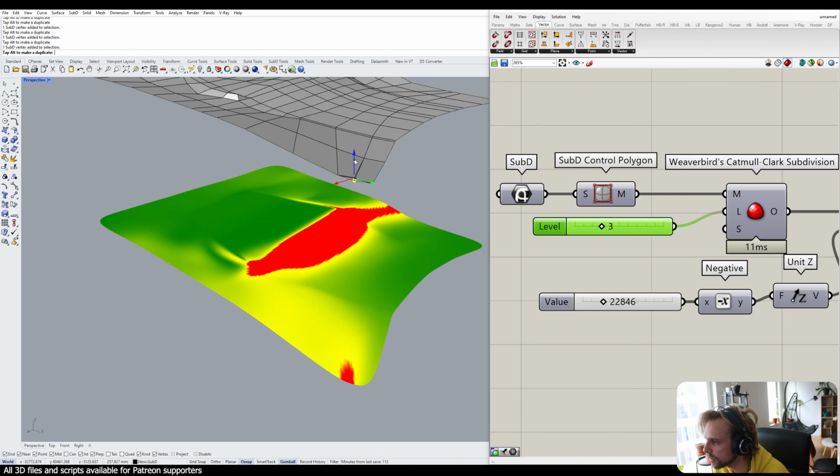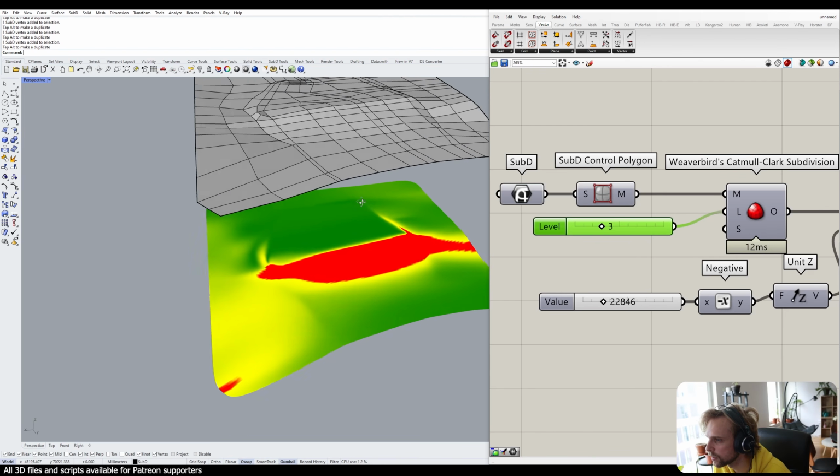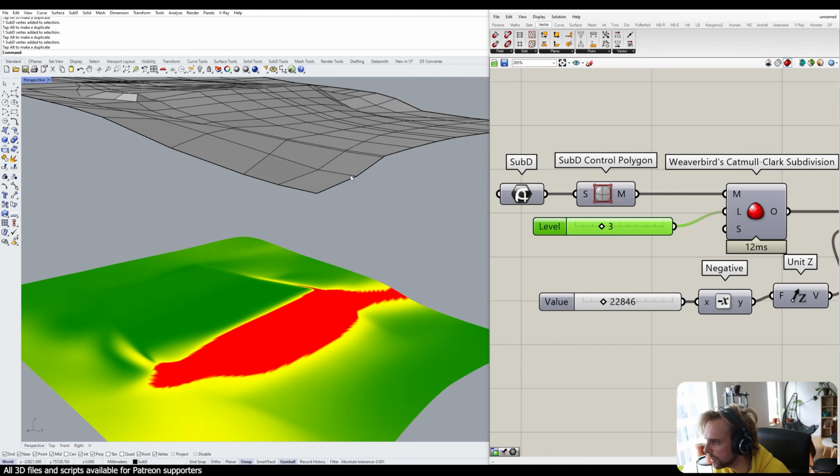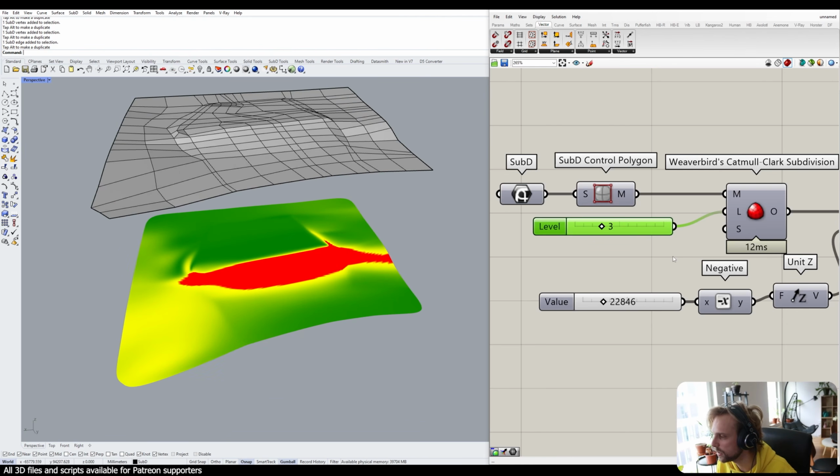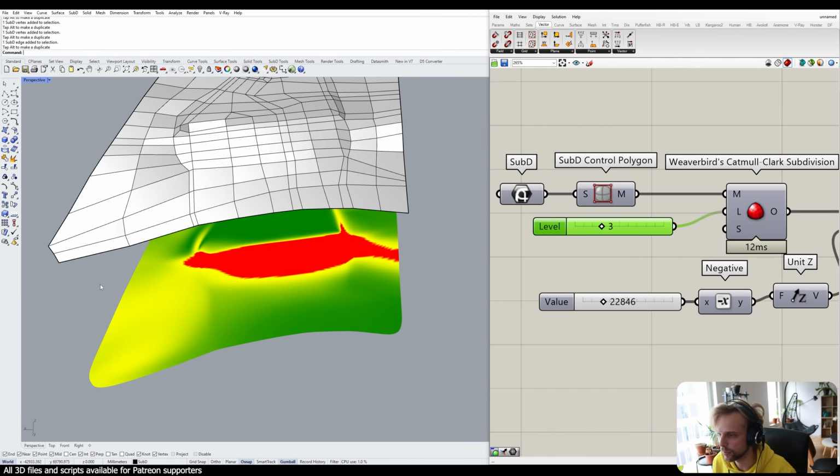And I'm just slowly moving all of this up until I won't see any red. I really want to move this whole edge up though. Let's try. Yeah, there we go. So now this is yellow, but it's within the bounds, right? So I don't need to worry about it anymore. It's going to pass the inspection, so to say.